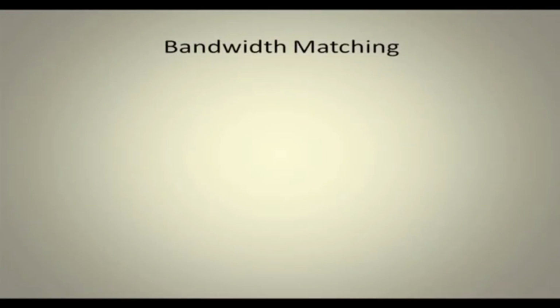Matching problem. We have a fast ATE, and the core testing is slower. So this ATE can provide data at a higher rate, and the testing has to be done at a lower frequency. That is the problem of bandwidth matching.